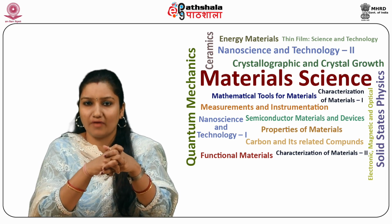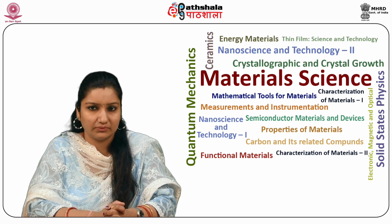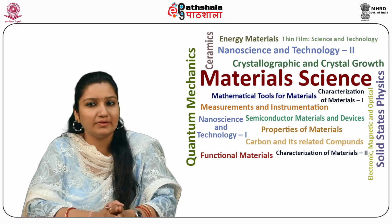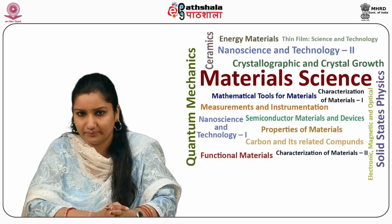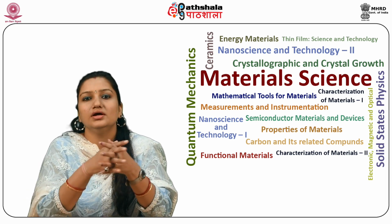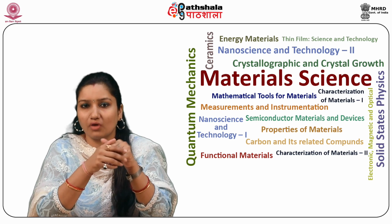Sputtering is a high energy fabrication method to produce thin films, especially for obtaining stoichiometric thin films, that is, without changing the composition of the original target material. Target material may be some metal, alloy, ceramic, or any composite material. Sputtering is also effective in producing non-porous compact films. Sputtering is an efficient technique to deposit multilayer films for mirrors or magnetic films for spintronic applications.